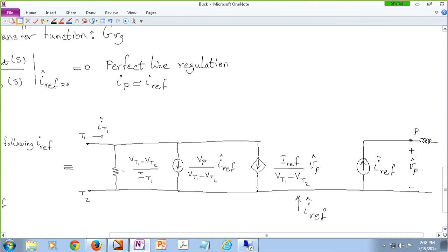Okay, so this is a generalized current mode control model for a single pole double throw switch. So in case I give you a homework assignment to use this, like for the boost converter, developing all these transfer functions, I'm expecting you to do this: identify the single pole double throw switch there, take it out, replace it with this, and then go ahead and solve the model.